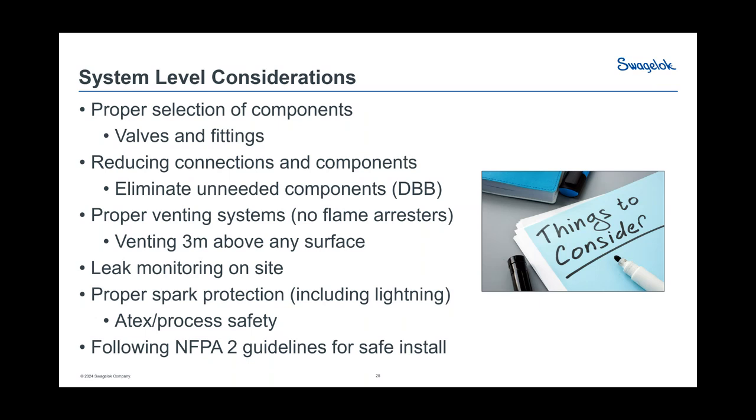You need leak monitoring on site. So leak monitors are used a couple different ways. One of them is using the potential for ultrasonic, but it doesn't usually work really well in loud facilities if you've got other things going on. But you can have ultrasonic, you can have sniffers that are actually smelling for the hydrogen, and then flame cameras, and you actually interlace all of those in systems. And there's companies out there that design those. Draeger is one of the great ones out of Germany that can teach how to do the entire system.